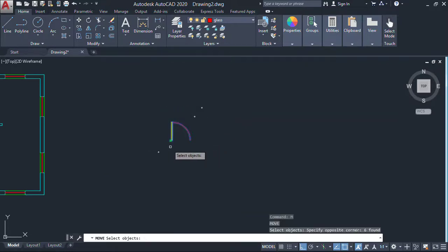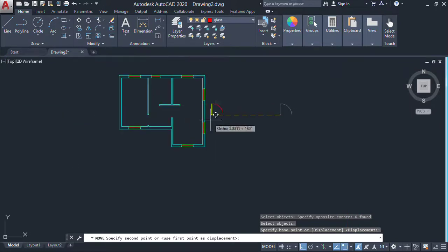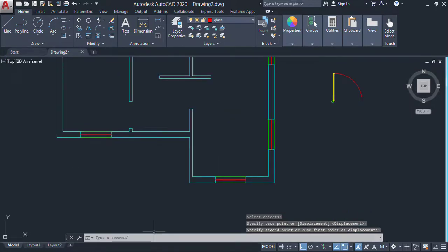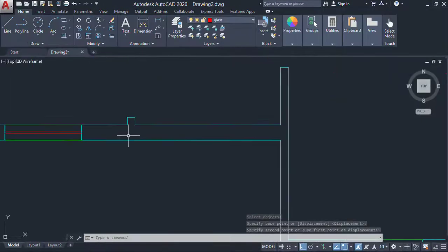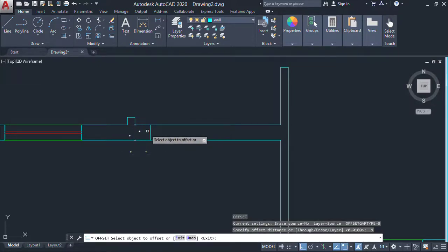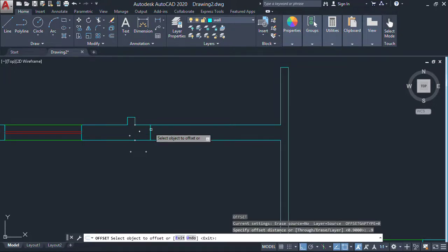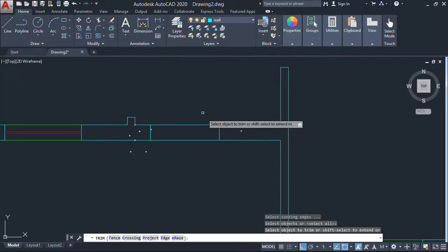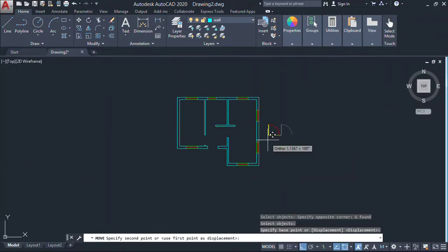I'm gonna move it here, since I guess I had a door here. Let me check my picture one more time. Yeah, I had a door here, so I forgot about the wall and to trim it. So I'm gonna just put a line here, move it about 20 centimeters, and it's gonna be another 19 because it's a door, so offset or copy, both can be correct, 90 centimeters, and then trim the middle, and then you can easily move your door in the middle of this.